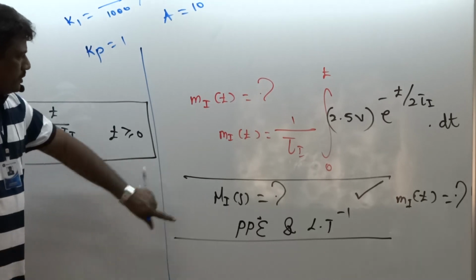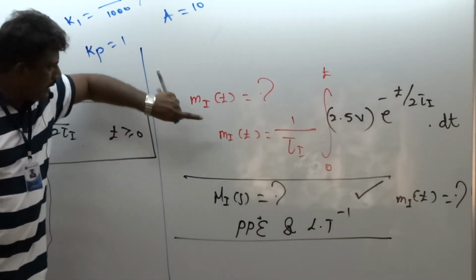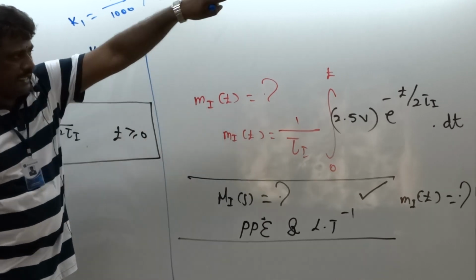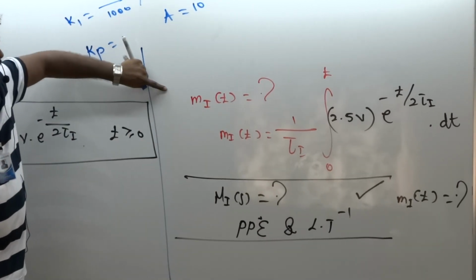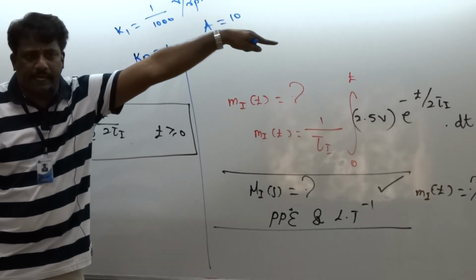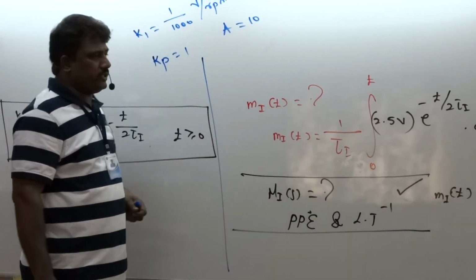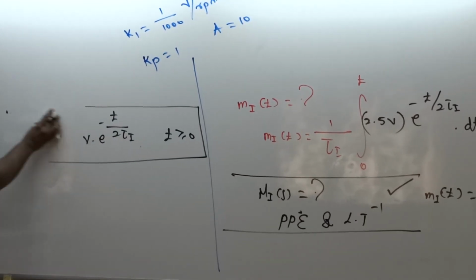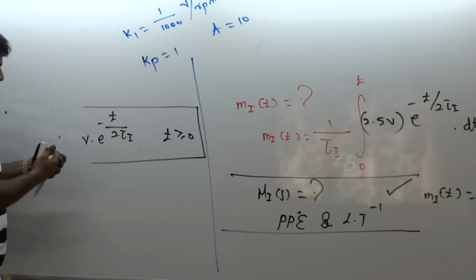Instead of taking this route, since error is available, we take the time domain integration so that you can understand how the integrator integrates the direct signal in continuous time domain and increases its output till error becomes 0. Okay, right. Let's integrate it now. Find out this process.